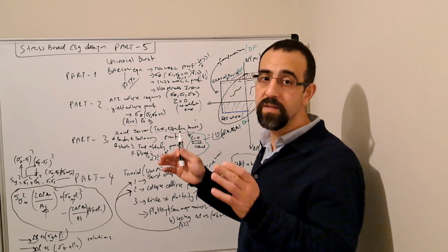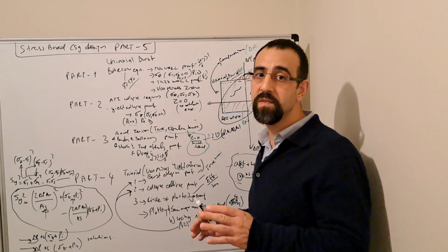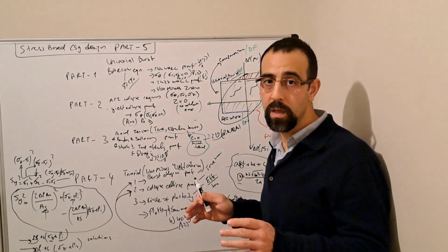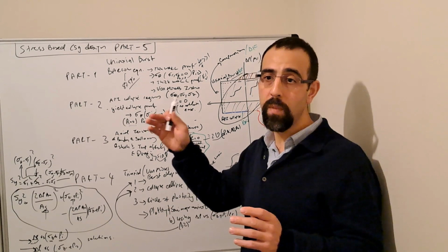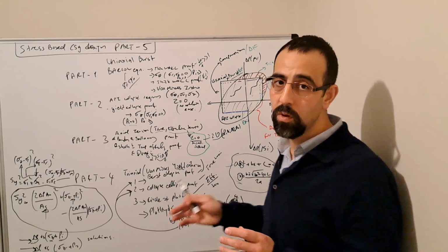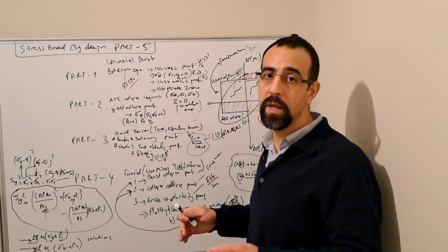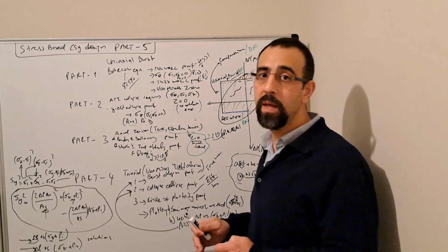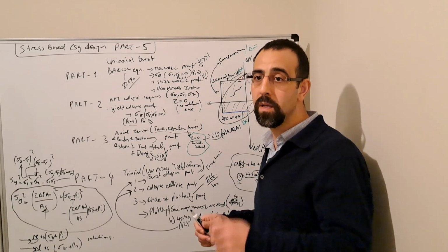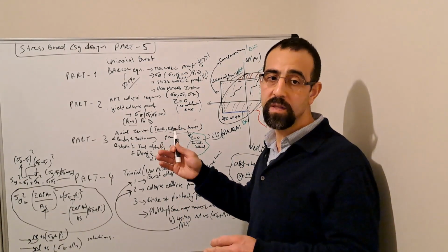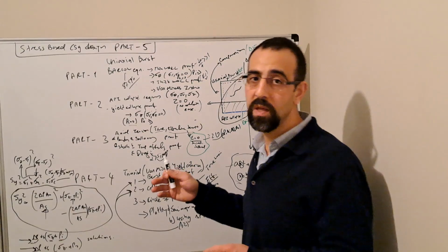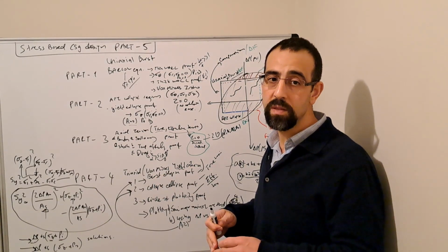We looked at a case where the casing is cemented and there are some initial conditions. You have the mud, spacer, and cement weight on the outer area, and then you have the mud inside, and then you bump the plug and take it up to the casing pressure test value with green cement, and then you take the pressure out.